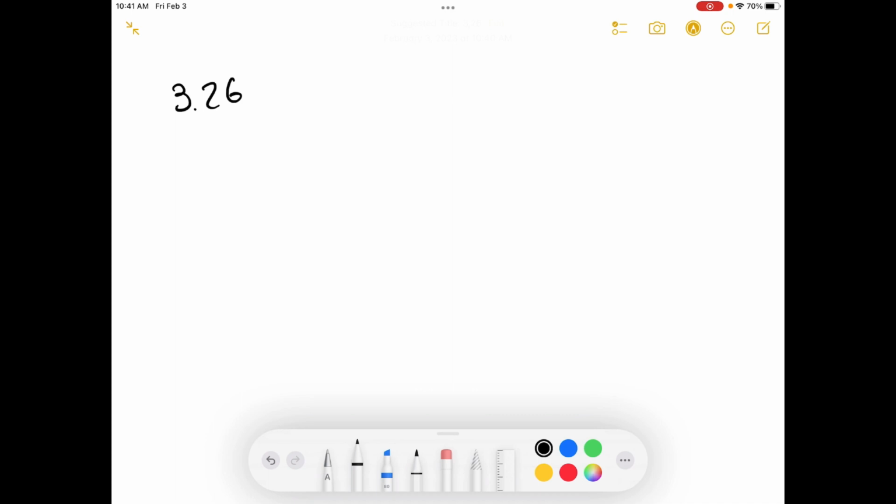The number of moles is proportional to the proportionality constant times the peak area, where A sub i is the area of the peak corresponding to the ith species. The proportionality constants, K sub i, are determined in separate calibration experiments in which known amounts of the components are injected into the GC sample port and the corresponding peak areas are measured.